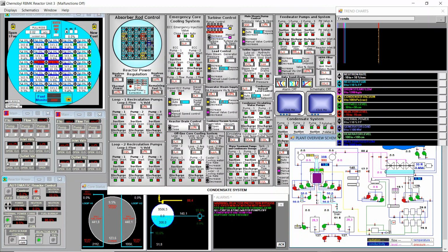And now what is happening is that this condenser lost the ability to condense steam that comes from the turbine. And actually in this simulation it's not going through a turbine because I showed you the turbine is in turning gear. All this steam is bypassed. So it's going through this channel here and then bypass and then condensed. Because the condenser is not cooled anymore, the steam cannot be condensed, and all the water that we pump with this pump here to the treatment is reducing the level of the hot well.